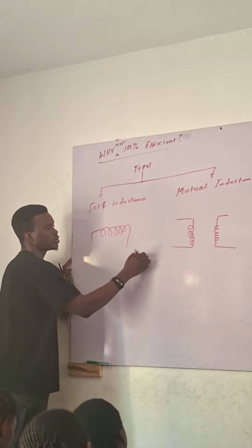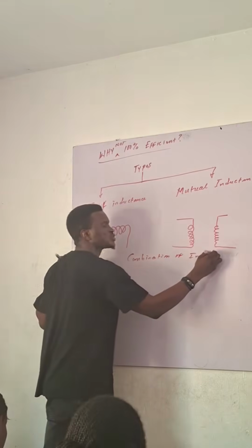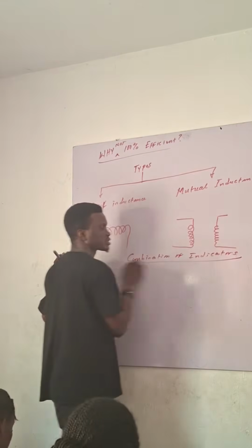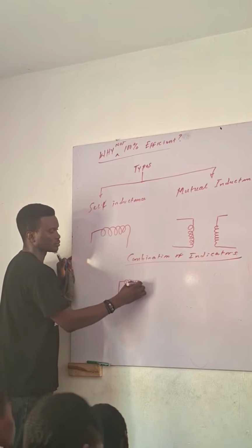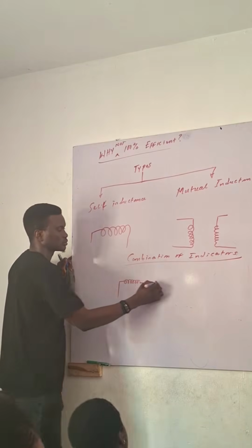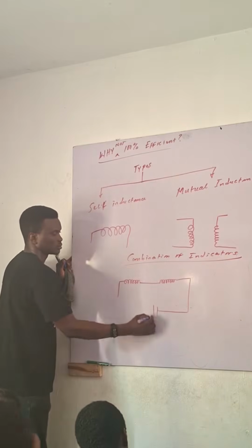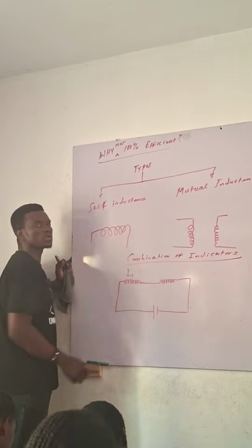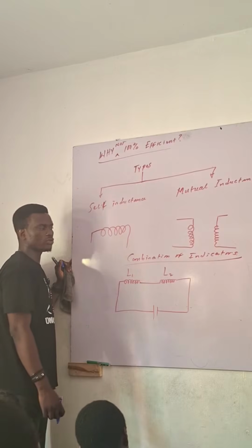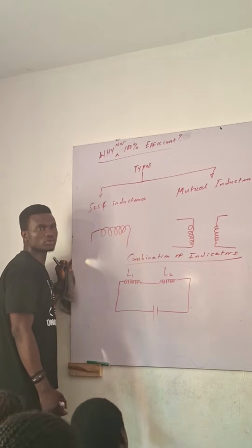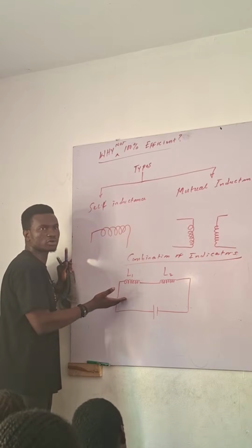So we can combine inductors, just the same way we have it for resistors. You can combine inductors in series. This can be your L1, this can be your L2. When you combine resistors in series, do you add or do you do the inverse? You add. It's the same thing for inductors.